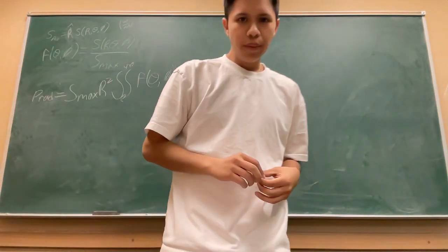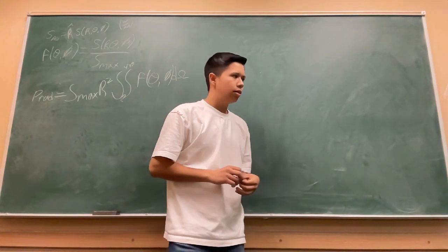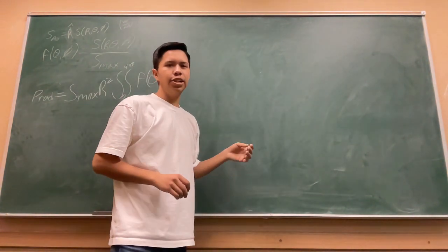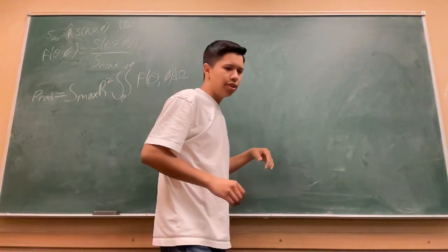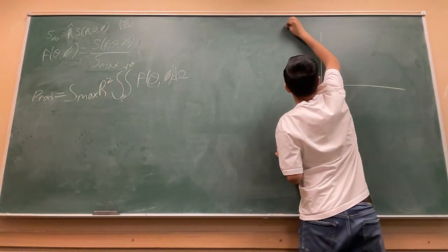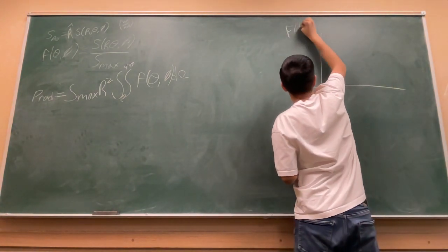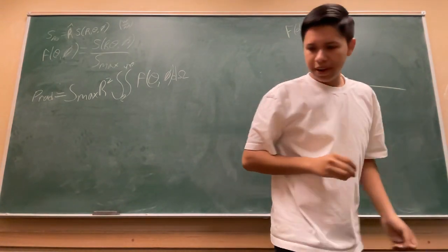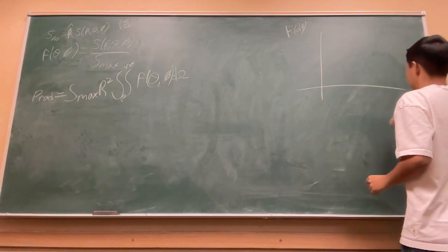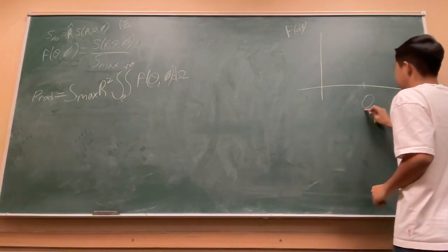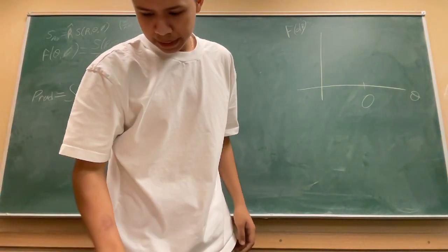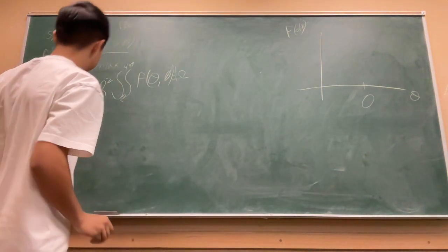So when we're plotting, we're going to plot the normalized radiation intensity. We're going to do a 2D plot, but you can also do a 3D plot where you're changing your theta and your phi value. But we're just going to do a 2D plot when we're changing our theta value. So we're plotting the normalized radiation intensity in decibels over theta. Actually, before we do that, let's write the equation for our pattern solid angle.